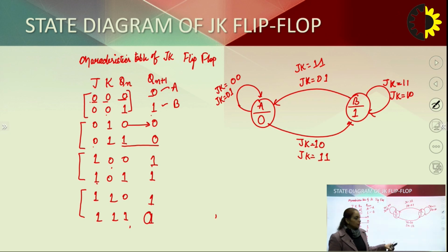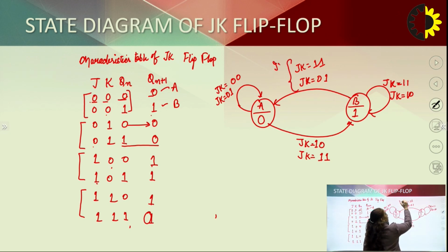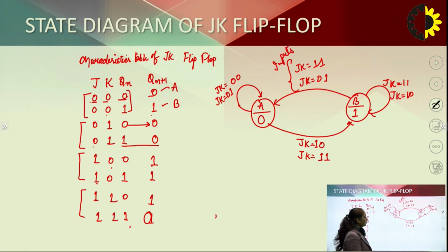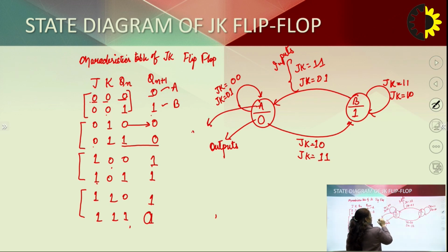Because in this state diagram I have represented the inputs on the transition arc and outputs with the state, it is a Moore representation.